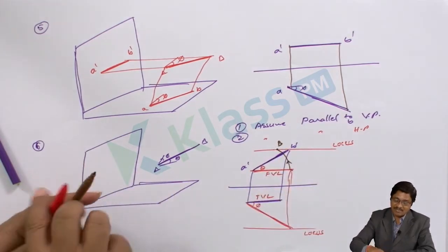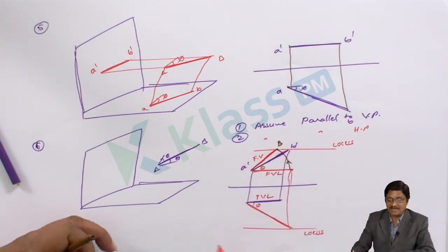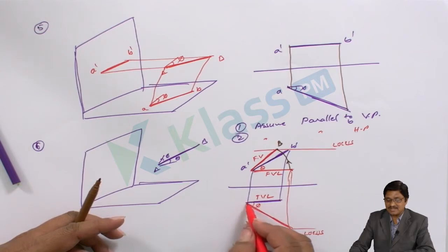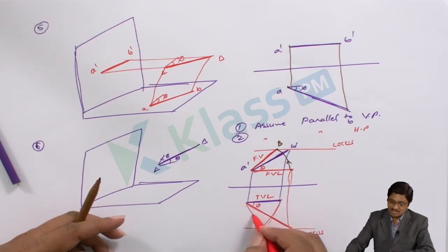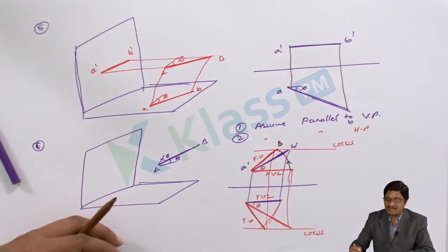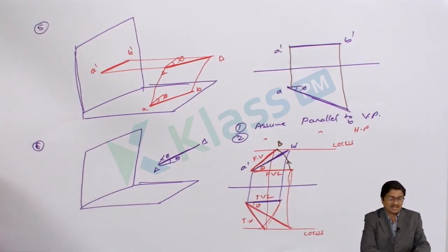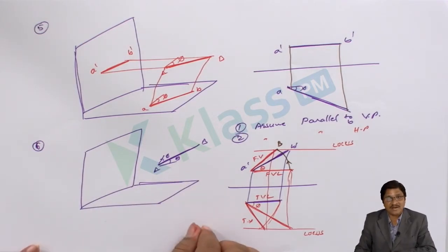Once you get the B point, simply connect with the point, which is the actual front view. Similarly, with the top view length as radius and this point as the center, I can draw the arc. Where it intersects, that point is to be connected, which is the top view. So you can cross check: front view and top view are always on the same line. So this and this must come in the same line. All these are complicated positions compared to that one. This is the little one. Directly we cannot draw, being the complex angle with both the planes.